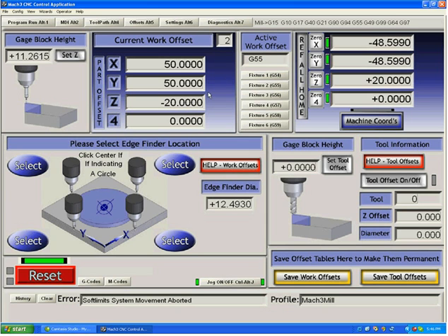So now, in terms of machine coordinates, and you always look at your settings of these fixtures in terms of machine coordinates, we are 50 away from the home switch in the X, 50 in the Y, and 20 down in the Z from the home switch to this particular jig that you have on the table.